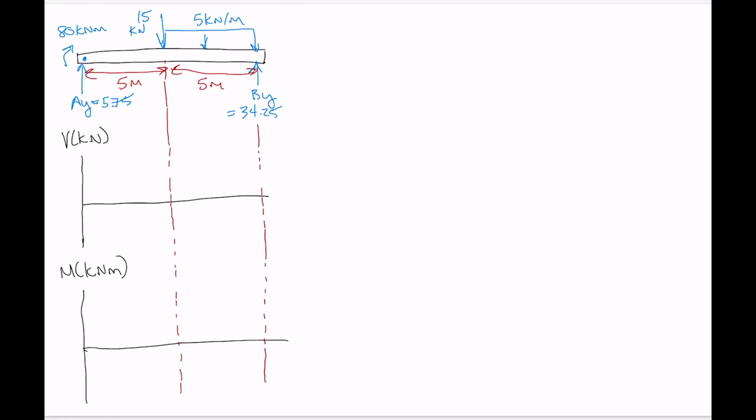Okay, so the second step when you're doing the method of sections is, working from our left-hand side of the beam, we want to take section cuts between every point load and within every distributed load, and then analyze the free body diagram of the left-hand portion of the beam for each of those section cuts and write equations for what the internal shear and internal moment is.